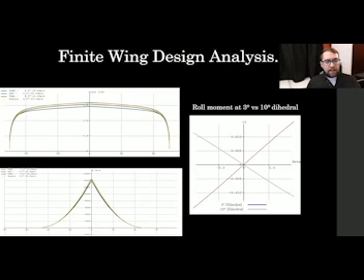You can see that the max lift coefficient is still above requirements, and by viewing bending moments you can also see a high structural requirement. Lift degrades sharply after approximately 90% outboard of the wingspan. Inspecting side slip response and rolling moment showed the wing was highly unstable. Increasing dihedral to 10 degrees solved this, but may need reducing once the higher wing is mounted to the fuselage, so further testing would be required here.